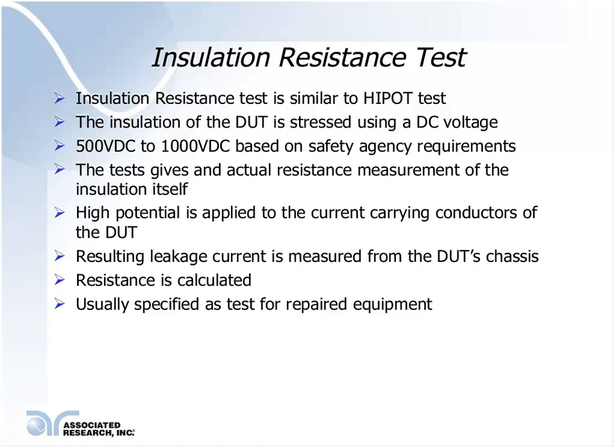Whereas a Hipot test provides a leakage current value, remember how we stress the insulation of the DUT in a Hipot test and measure the resulting leakage? Similarly, the insulation resistance test gives us a resistance measurement of the insulation itself.